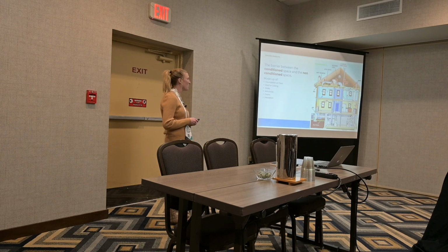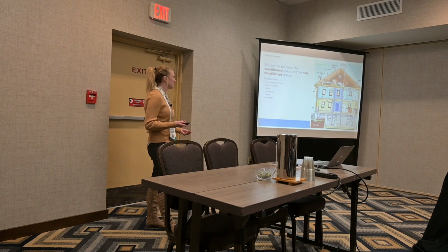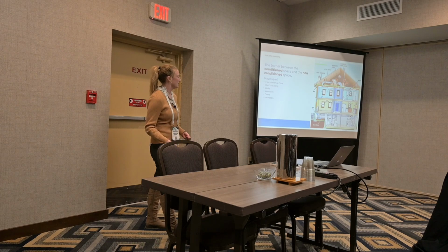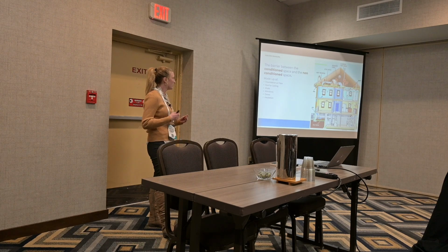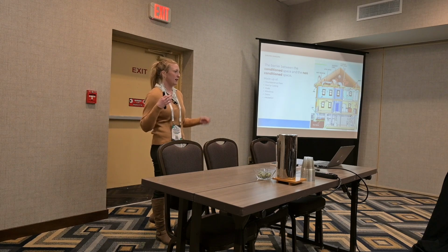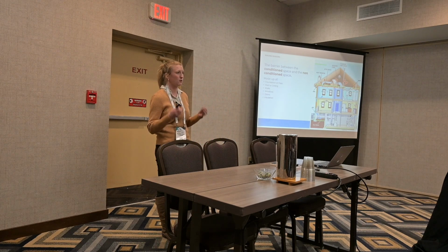When assessing the home, you want to understand what the building envelope is. The building envelope is the barrier between the conditioned space and the non-conditioned space. It can be made up of the foundation or floor, roof or ceiling, walls, windows, doors, and other insulating surfaces. So you want to understand that barrier to make sure you're capturing all that data for the load calc.